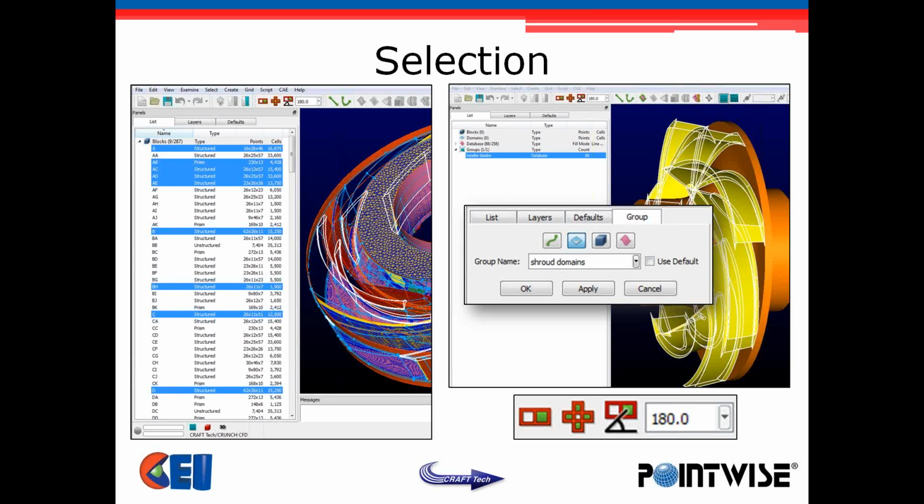So creating a group allows you to quickly batch select a bunch of entities and then operate on them. And I've highlighted this adjacent select tool because we haven't talked about it too much in the past, and it allows you to select one adjacent entity or all adjacent entities based on an angle limit. So that's another way to do some selection in Pointwise.